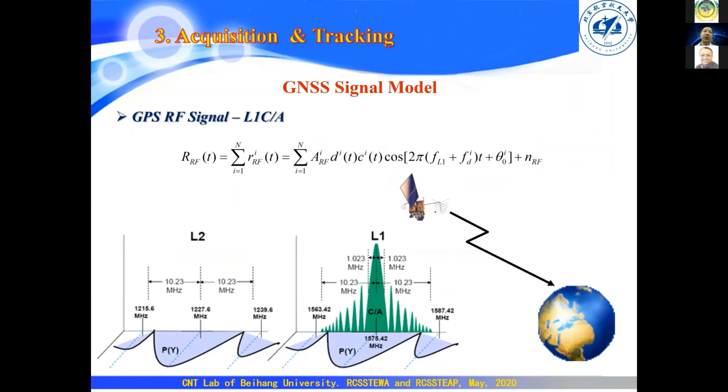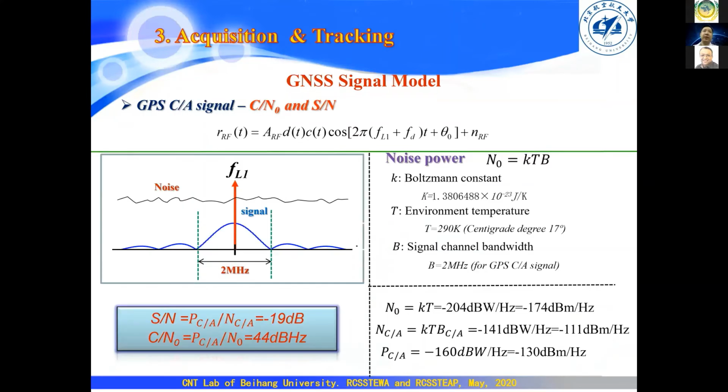So what we do is find the satellite in this area, the L1 frequency, and this is what we find in a cell phone. A similar approach can be done by searching for the L2, L1P and L2P signals. The signal is commonly negative 20 dB relative to the noise floor, so what we need to do is find this one.